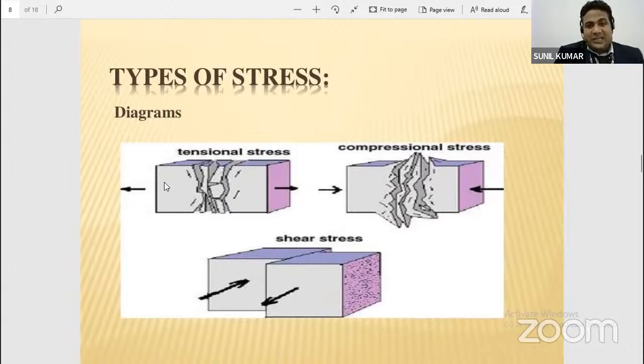Here sigma, the stress, is not constant throughout the section. Why? Because the nature of deformation changes inside the region. Layer by layer, the deformation changes, so stress always changes. So we cannot say that the stress is constant in a particular region. So sigma is equal to limit delta A tends to 0, delta F upon delta A.